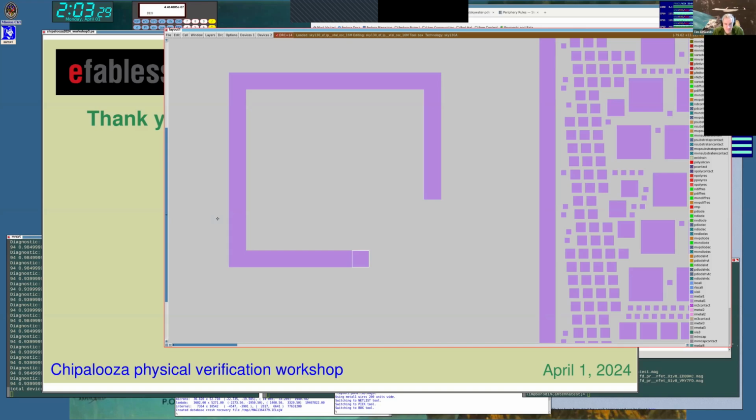Yep. Brady X asked, after extraction and modifications need to be made to schematic and layout, is there a quick way to update the layout from Magic with changes coming from schematics? Or do you have to do that manually? No, it's actually, I have a reentrant version of this, the file import spice. So if you have a layout and you import spice from an updated schematic, it should be able to find the things that changed, and it should modify just those things. Don't trust it implicitly, so make a copy of your layout just in case.